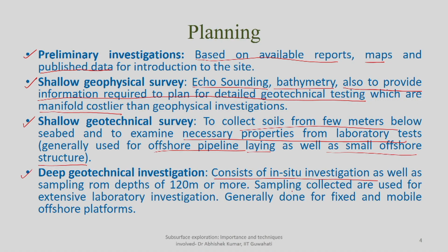Then sampling. This consists of in situ investigation you can do from the vessel which is available at the sea surface, or maybe at the seabed itself. So, this is when you are doing any kind of sampling from depth of 120 meter or more. This 120 meter or more is the depth below seabed. So, it is not the depth of water, it is rather depth from the seabed downward which you are interested to explore. So, this is generally classified as detailed geotechnical investigation.